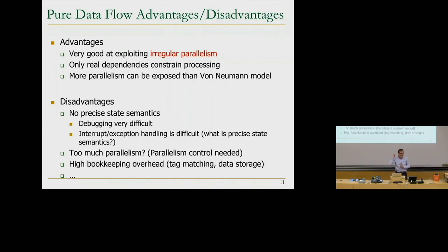So this is true not in an out-of-order machine, but a pure data flow machine. You can expose a lot of parallelism with a huge data flow graph, and you need to have a machine that handles that parallelism. Because if you don't have enough buffering in your machine, now you have the problem that you cannot keep track of which instructions are ready. You cannot keep track of the source readiness of the instructions. As a result, you may not be able to actually build a correct machine, or you actually need to store this data flow graph somewhere else, maybe on a hard disk, for example, and then keep bringing it in so that you can figure out which instructions are ready, but that's a lot of overhead. So as a result, this didn't work too well.